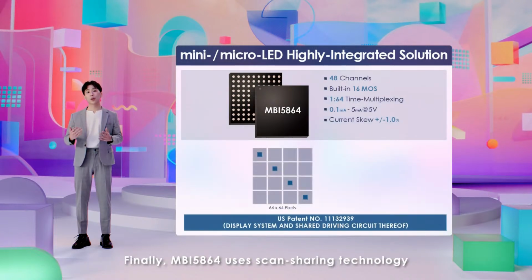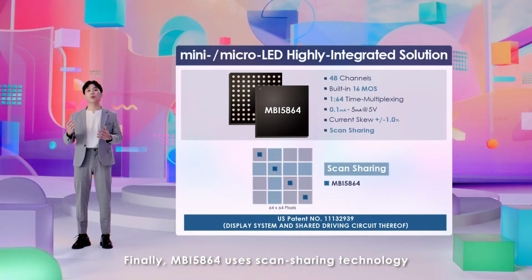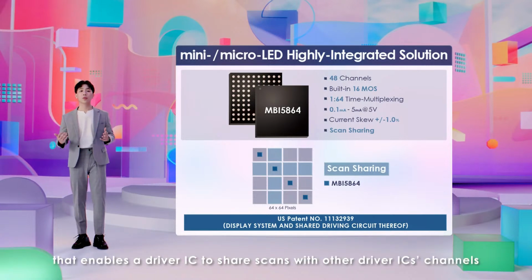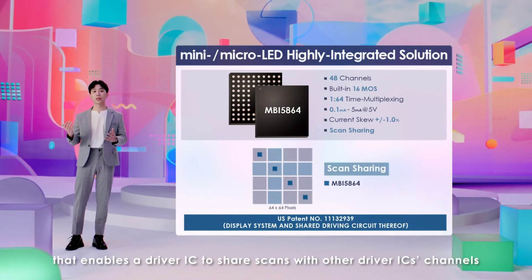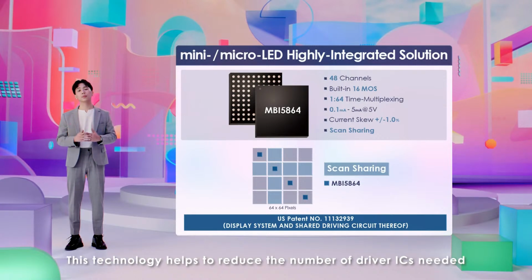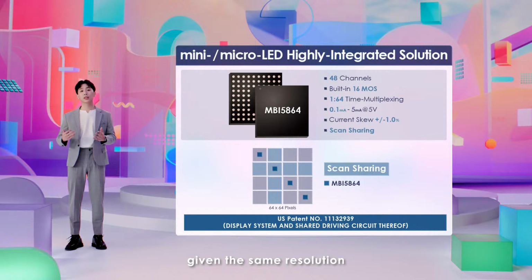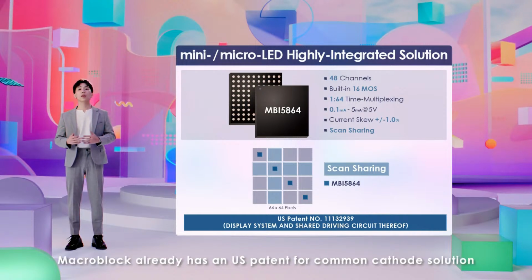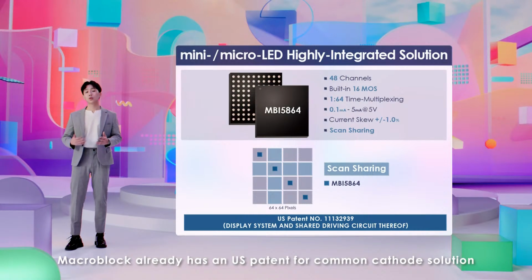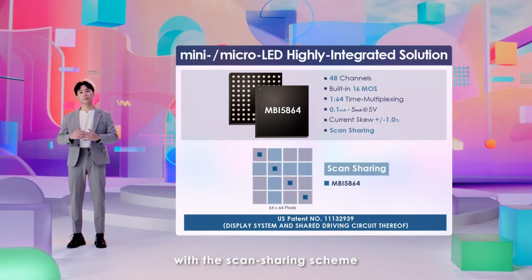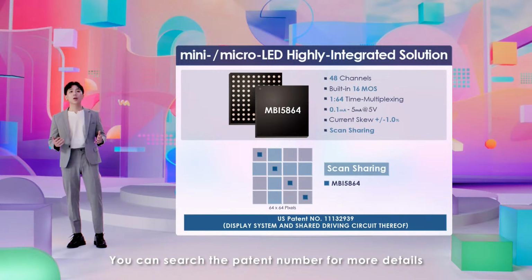Finally, MBI 5864 uses scan sharing technology that enables a driver IC to share scans with other driver IC's channels. This technology helps to reduce the number of driver ICs needed, given the same solution. As to the scan sharing technology, Macroblock already has a US patent for common cathode solution with the scan sharing scheme. You can search the patent number for more details.